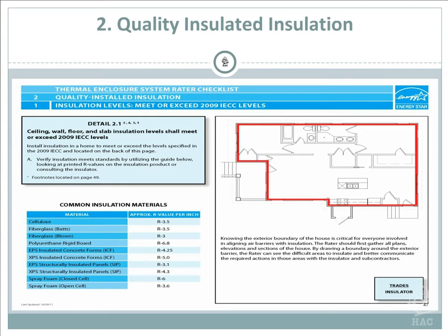So again, insulation. It talks about insulation. It says all walls have to be insulated and so on, and it gives you a breakdown. Again, common insulation R values are here. So it depends on what area you live in, and looking at your exterior or conditioned area, what are the R values that you're going to need? There's some high-grade insulation, there's some high-density insulation.